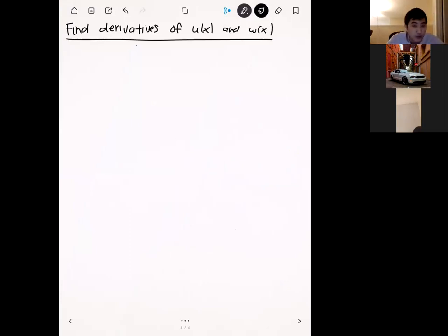And so if you remember from Tuesday, when we take the derivatives of these, the derivatives just end up being on the shape function terms. Right? So we take dw dx, we get w1 dn1 dx plus w2 dn2 dx, right? Because w1, w2, we assume that those are just constants, and so we're not going to take derivatives of them. Okay.